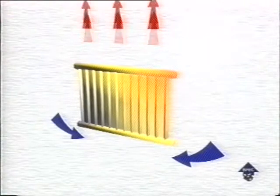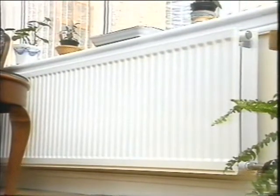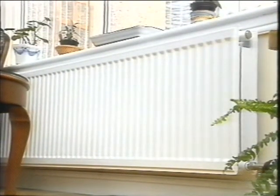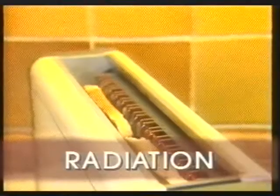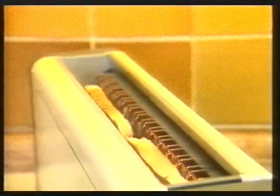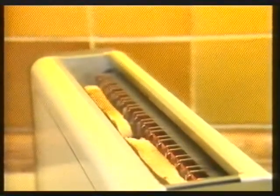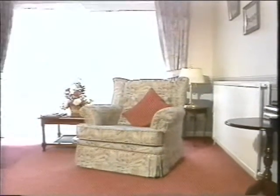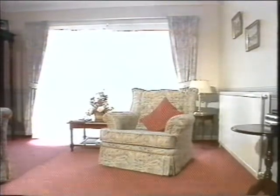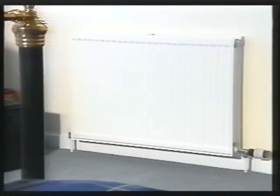Conduction and convection both need a material substance, a solid, liquid, or gas, to allow the heat to get from one place to another. The third form of transference doesn't. With radiation, heat is transferred from a warm object to a cooler one across a distance. It travels in straight lines, and heat energy isn't given out until it hits an object in its path. Some of it's then absorbed. In spite of their name, radiators emit most of their heat by convection, but they do also radiate heat. The proportion radiated can be increased by painting them darker and putting reflective material behind them.